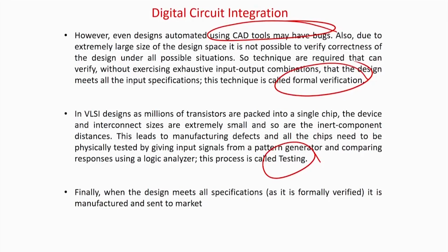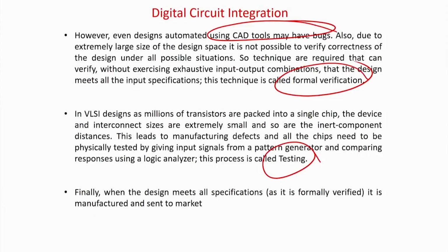But if the fabrication technology says that 99.9999% yield is there, then you know that almost every device is normal. Just with preliminary testing, you can ship it to the market, because you know that 1 in 1 million chips will be defective, so that I can easily replace. But here you cannot do that, because around 30% of customers will have a defective chip and you will be out of the market if you do that. So, therefore, testing is also a very important paradigm of VLSI design.